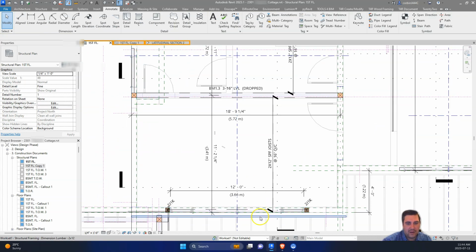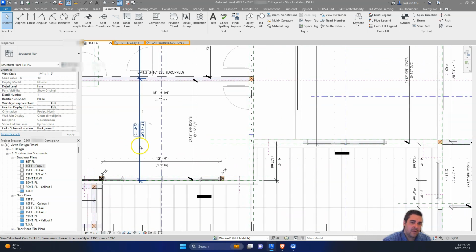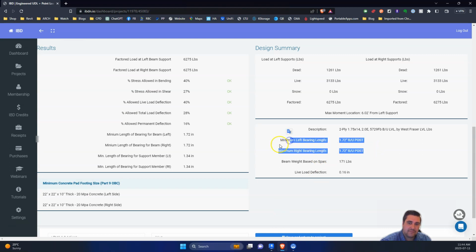So, one? Can we make it 2? That actually could be a potential. I would say with our stuff, it's usually always 1. The only time we would get 2K would be based on the engineer. So if we had an engineer... so that's stable, right? Like 2J and 1K is the stable? Yeah, it's the piece that's continuous. So that would just be based on the engineer. Typically it only specifies the jack posts, the bearing posts, not the actual king. 2J and 1K, I was thinking maybe could be not stable. Maybe no, the wall studs are all connected, and then the sheathing on the outside provides stability.